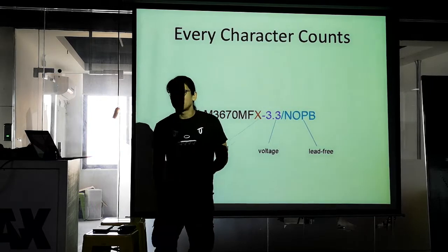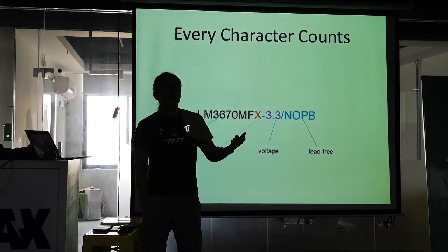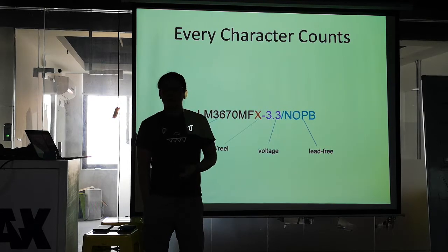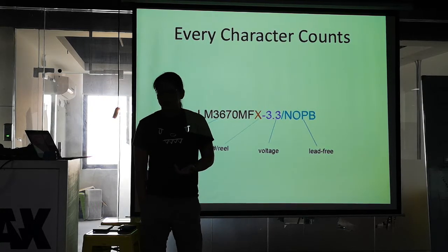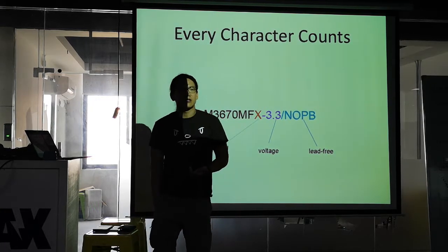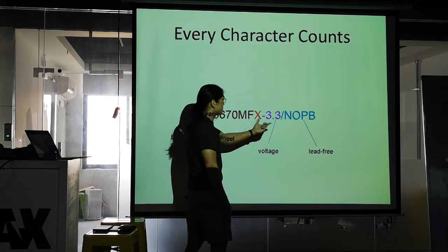No one wants leaded parts anymore today. They're like, oh, okay, this is great, we're getting very good pricing on the parts. But then you try to import it into Europe or Japan or something like this, where they have a lead-free requirement, and you can't get the certification for it anymore, right? It's because you left out this specifier, right?